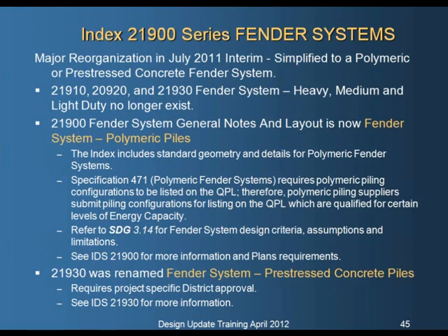So those piling configurations are approved for certain levels of energy capacity, and as part of the fender system design, the EOR for the project will be required to establish a required minimum energy in the plans and list that in the plans, so that the contractor can select a fender system that meets those minimum capacities.